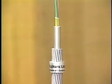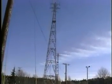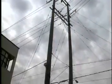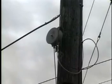The installation of OPGW cable is similar to the placement of conventional ground wire. However, even though OPGW provides excellent protection for the optical fibers, bend radius, pull tension, and twisting must be carefully controlled during installation. The hardware and accessories used with OPGW have been specially designed to avoid damaging the optical fibers. Conventional cable hardware should never be used.